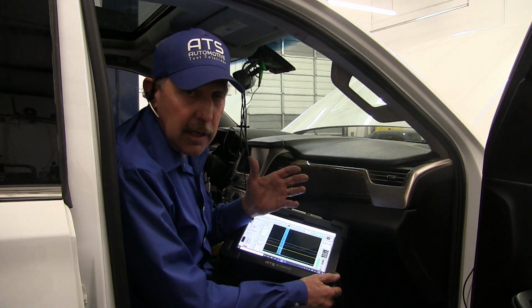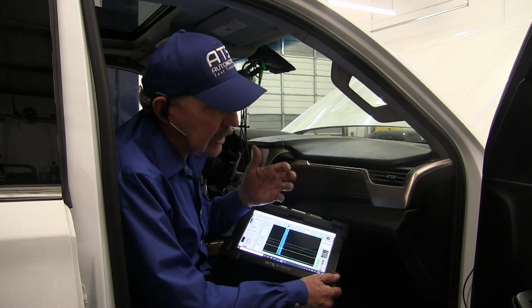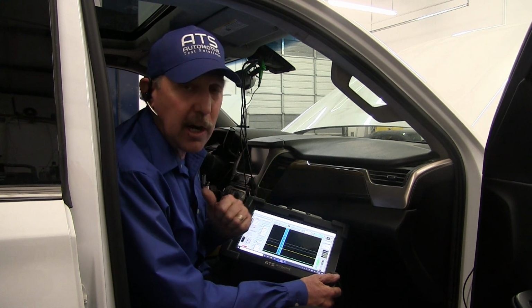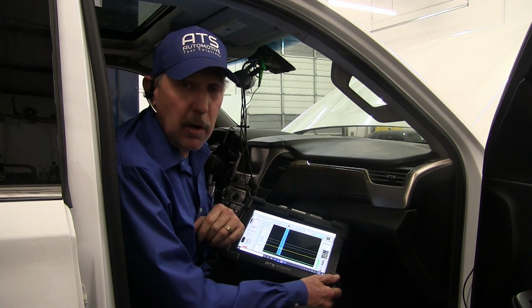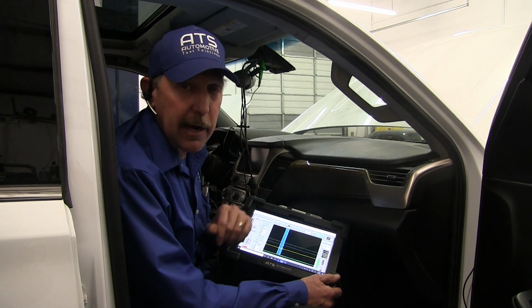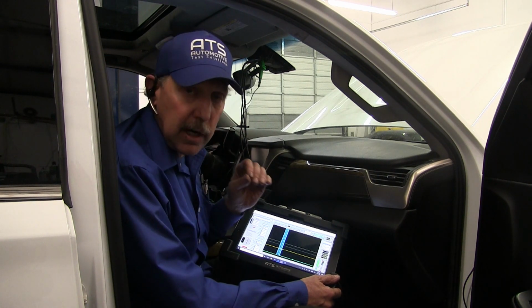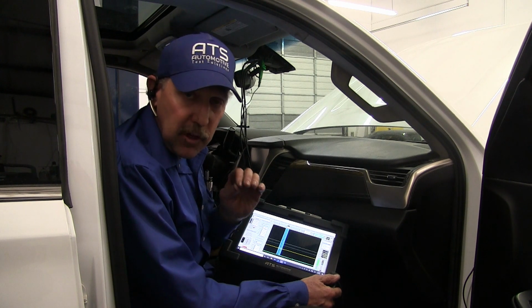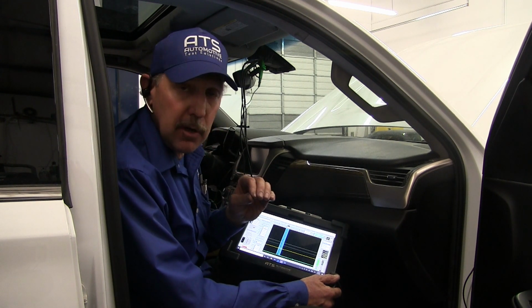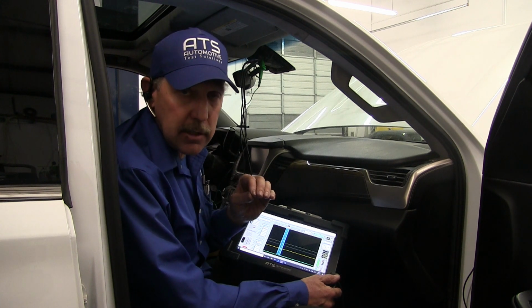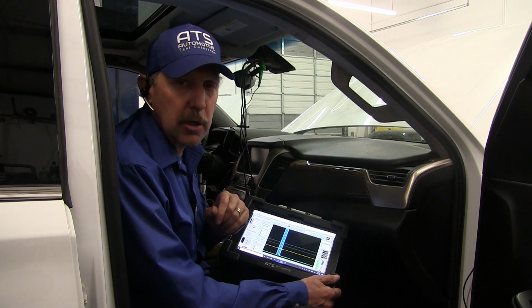The factory scan tool that we used sort of confused us because it said this is an intermittent problem or a history problem, it isn't current. This system never worked the whole time we worked on the car. That wire is open, that's why the car's here. The shop's going to fix the wire, and we're going to deliver the car. If you follow some basic guidelines for communications diagnostics, such as I've laid out, you too will have good troubleshooting in your base.